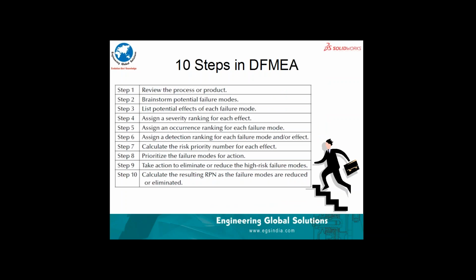Listing the potential failure effects of each failure mode forms step number 3. Assigning a severity ranking for each one of them, step number 4. Assigning an occurrence ranking for each failure mode, step number 5. Assigning a detection ranking for each one of them, step number 6.